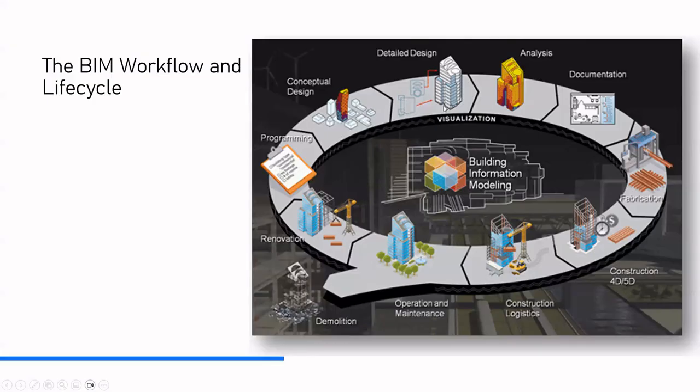and the analysis side of it, this is where the visualization aspect really shines, and being able to communicate those results, whether it's the potential efficacy of your solar panel arrays, or the thermal impact of your facade choices on your building, or the implication of concrete. And I think one of the growing aspects where we're seeing more and more focus now is the embodied carbon impact of the project. This is where BIM has an incredibly important role to play, by being able to quantify and codify those CO2 emissions that are locked into the building from the outset. So we're seeing a lot more focus on embodied carbon now.